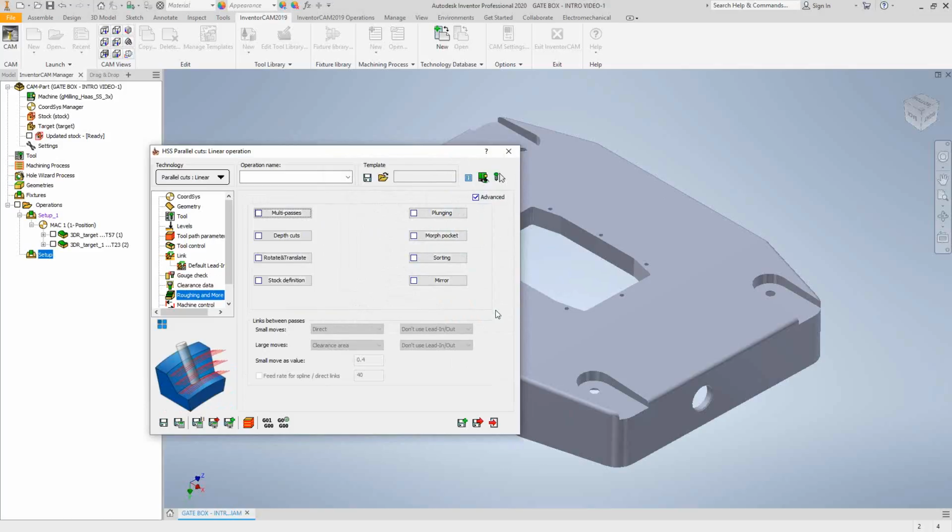So this is the only 3D toolpath available in some packages. In the 2.5D Standard and 2.5D Pro, you don't get 3D toolpaths, you just get this one, which is the only 3D toolpath you get. Now, let's generate that toolpath and take a look at it.